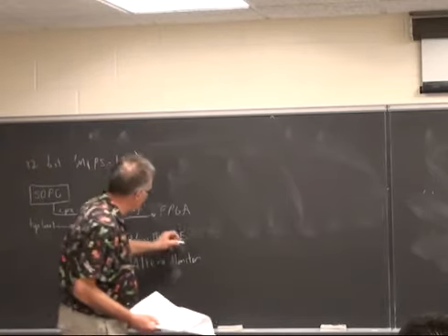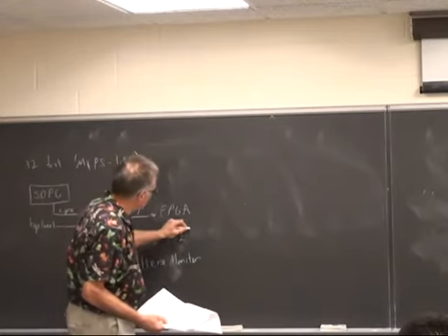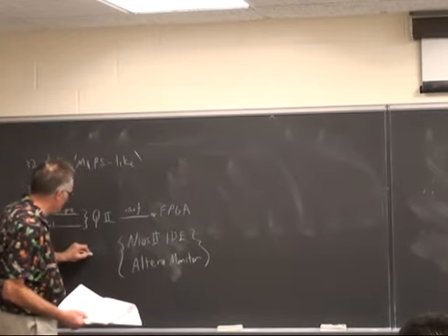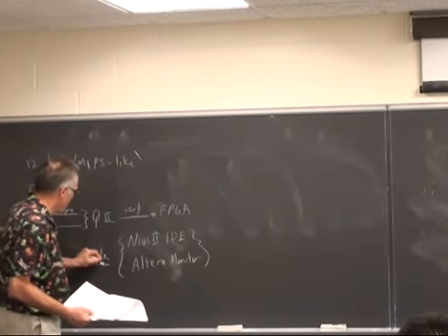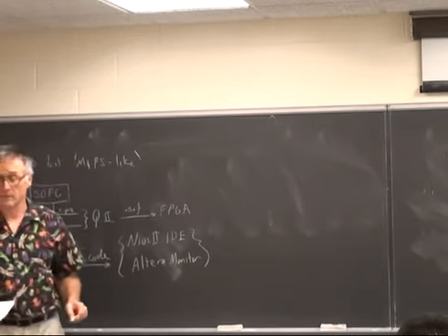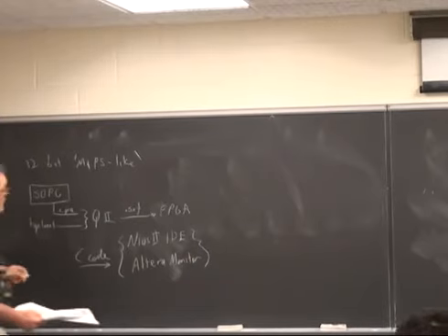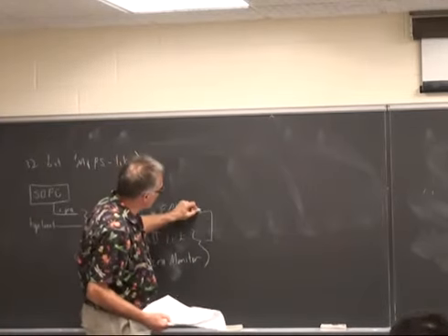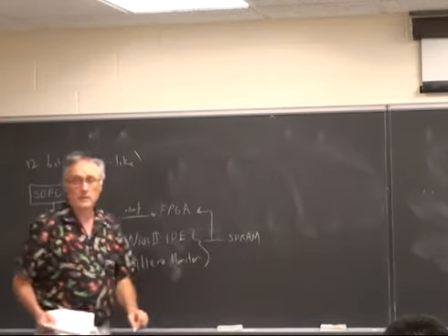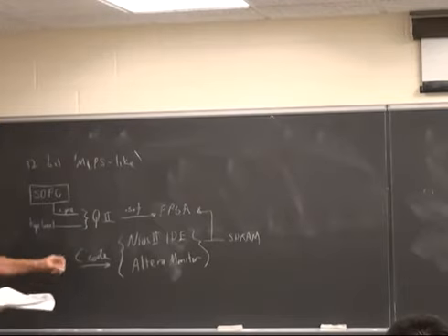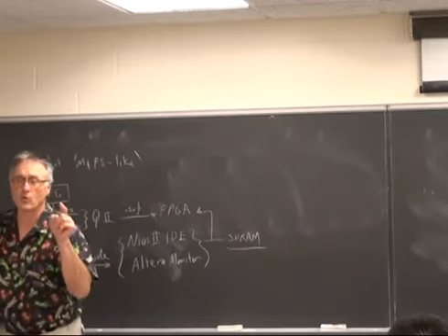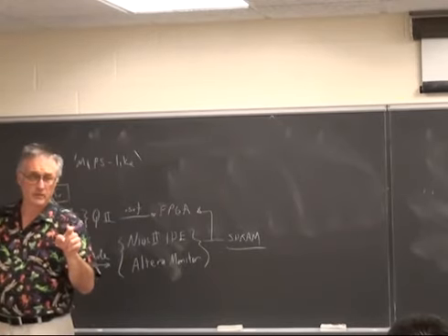So there are two different ways now of generating C code. The input to this is C code. Or if you're feeling really brave, you can code in assembler, in MIPS assembler. And then this is either going to be downloaded to the FPGA or to SDRAM, depending on exactly how you want to execute this. However, if you download to SDRAM, you need to read the SDRAM tutorial, which is also linked up in Lab 4.